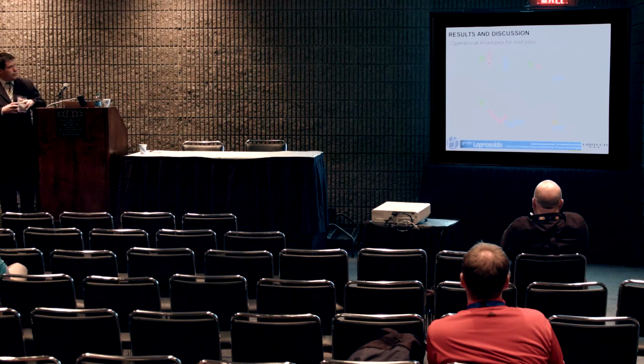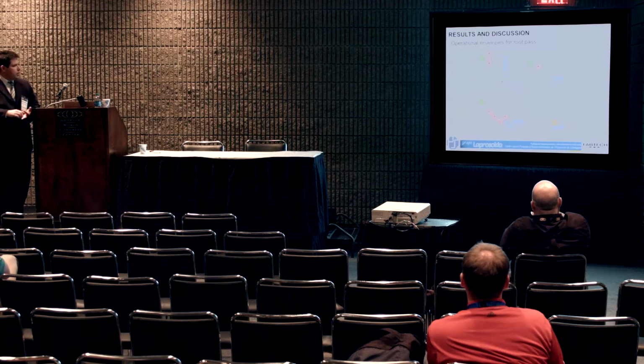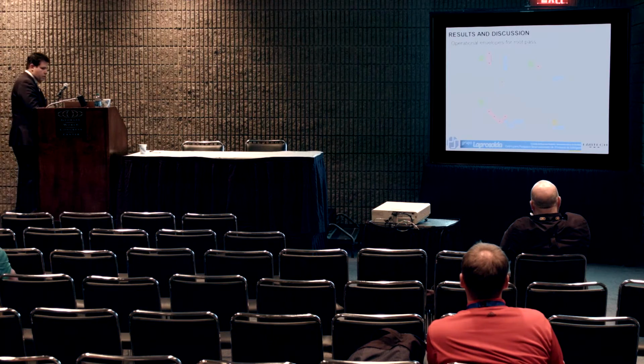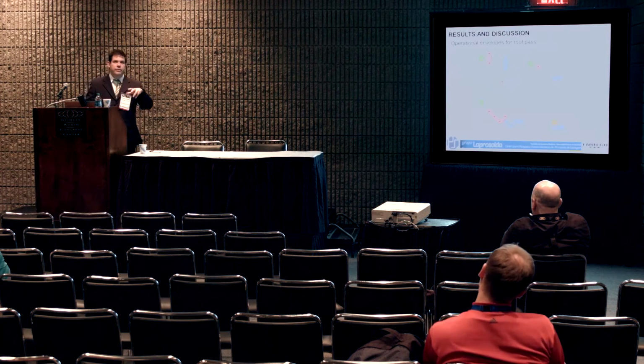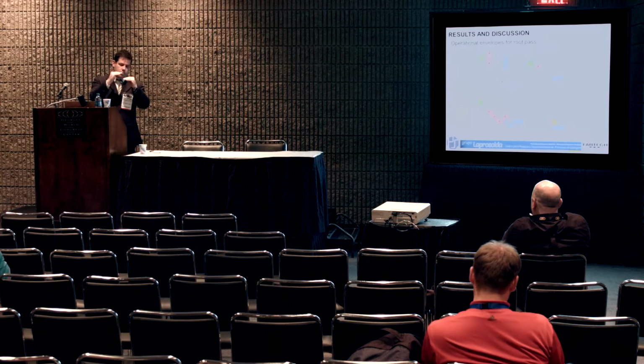Here's a set of the envelopes that we got for the root pass. Basically it says you can weld with conventional MIG, you can weld with RMD, with STT, with CMT, you can weld with all of them. For the root pass, we did pure CO2 and argon plus 25% CO2, with and without 1/16 of high-low.